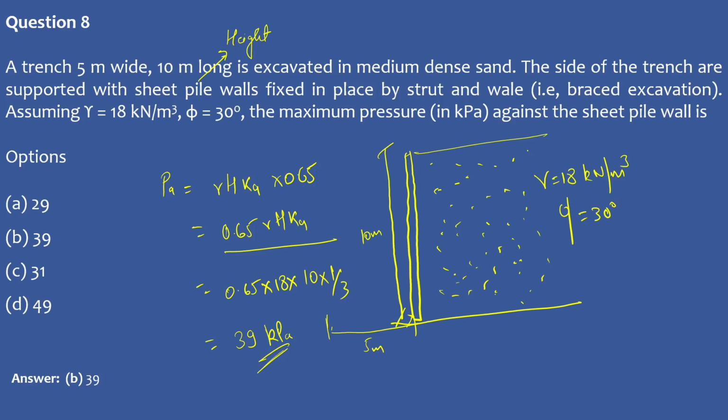In geotech, mostly there are things which are mechanics derived, but since the soil is highly heterogeneous for various locations and has high variability, you can't apply the mechanics for a global system. So you need to derive some empirical relations for a certain site, and you need to reduce strength somewhere, overestimate the strength somewhere, by considering specific cases.